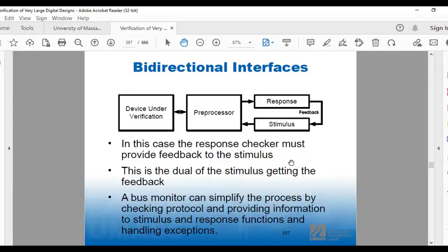It's a bidirectional driver. So if you look at the code for a bidirectional driver, that's what this is. It's kind of the dual of what's in here. It's a behavioral model of it, but it's the same kind of thing. So it's a driver this way, a driver this way, the receiver, the transmitter into here can be tri-stated. You've got more checks in there because you have to check to see whether it's high or low. I don't really see when it's enabled or not, but that has to come from the stimulus. So there's really two things coming from the stimulus.